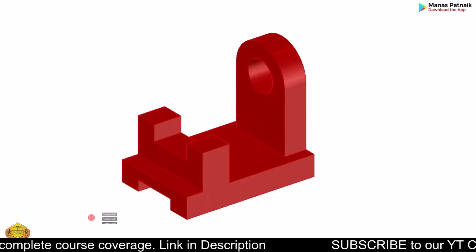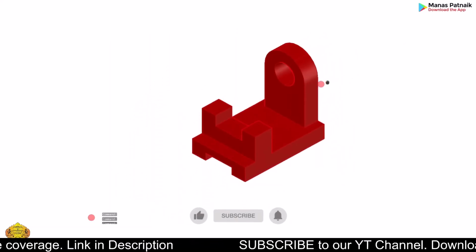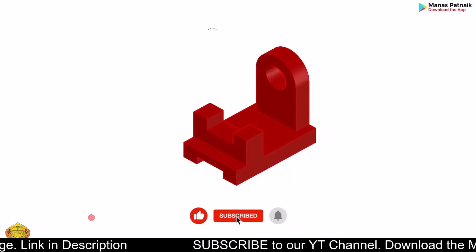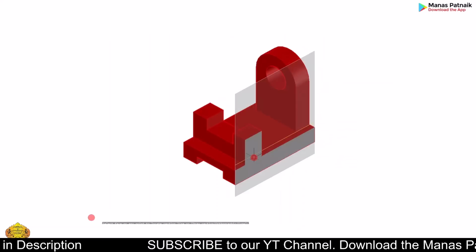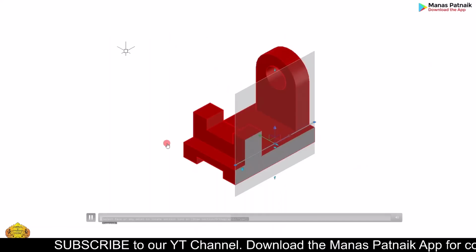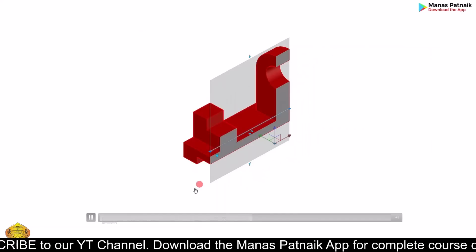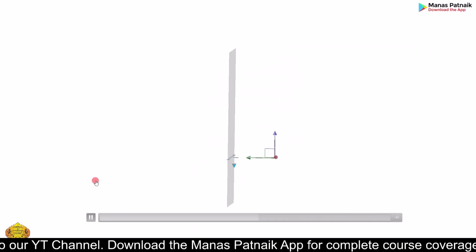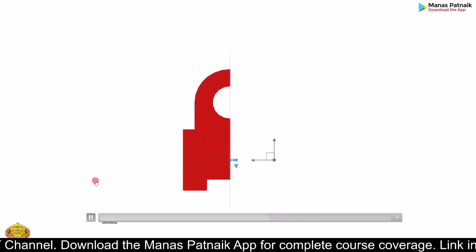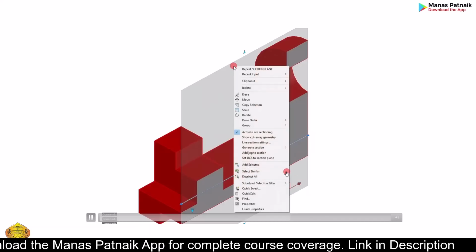Now what we wish to do is we wish to bring in a cutting plane or a section plane, okay, which is going to pass through the line of symmetry that I just showed you just a few seconds back. Take it behind in this direction. You'll see this is what you need to do. Okay, and from here you are going to make the sectional front view.